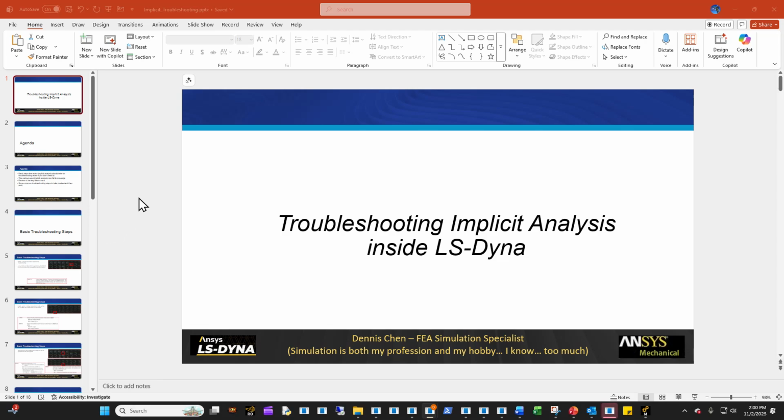All right, today let's look at implicit analysis inside LS-Dyna and how to troubleshoot it. If you've ever done implicit problems, the biggest headache is sometimes the model just doesn't solve because it failed to converge. So let's look at how to do some basic troubleshooting.